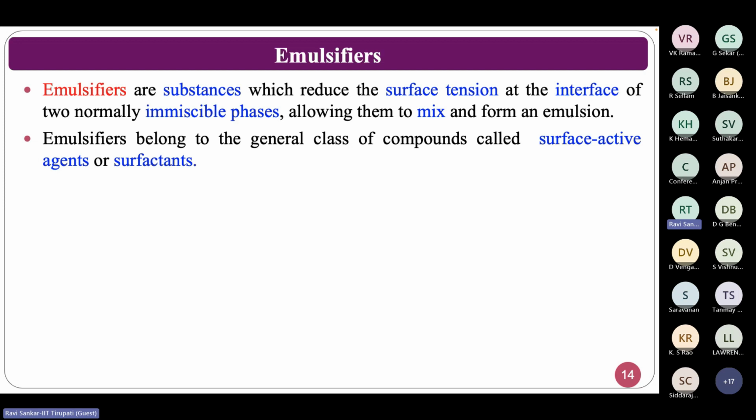So the first and foremost additive that you have to look at is emulsifiers. The major function of an emulsifier is to reduce the surface tension between two immiscible fluids. For example, you have water where you just put some drops of coconut oil. What will happen? Both will not mix because the surface tension of the coconut oil is completely different from the water. In those circumstances, you need to add some emulsifiers which make the surface tension between these two approximately equal. When the surface tension between these two is approximately equal, what will happen? This will dissipate or fragmentize into small fragments.